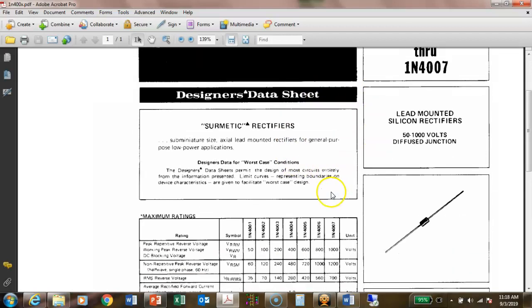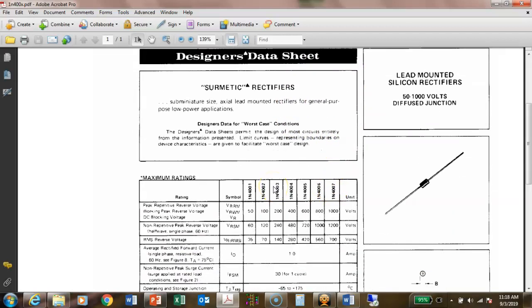So unfortunately, books teach PIV for peak inverse voltage, but just about all your data sheets will call this the reverse working voltage, VRRM. So that means that's something I should have checked before I put this diode in here. I should have made sure that it had the ability to block that negative alternation, right? You understand that?